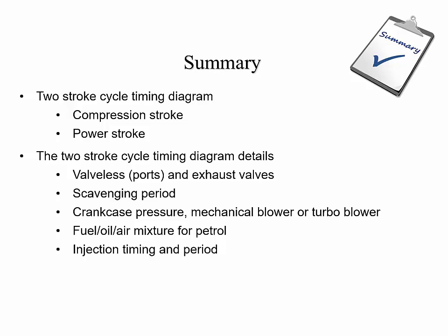For a petrol two-stroke, there is no lubricating oil in a sump as such. So the lubricating oil has to be mixed with the fuel in the correct ratio, and this provides lubrication for all the moving parts in the crankcase. So we talk about a premix of fuel and oil. The lubricating oil for a two-stroke engine is different to the lubricating oil for a four-stroke engine.